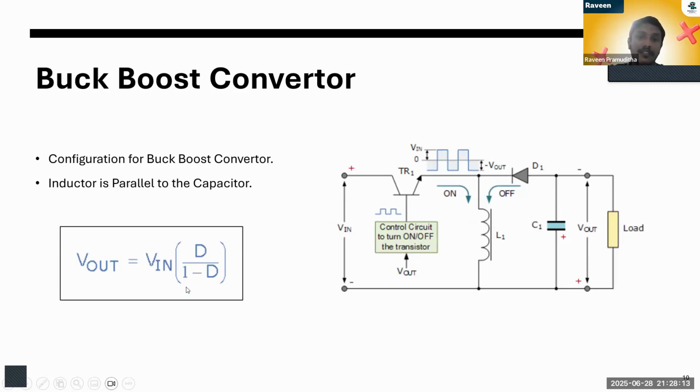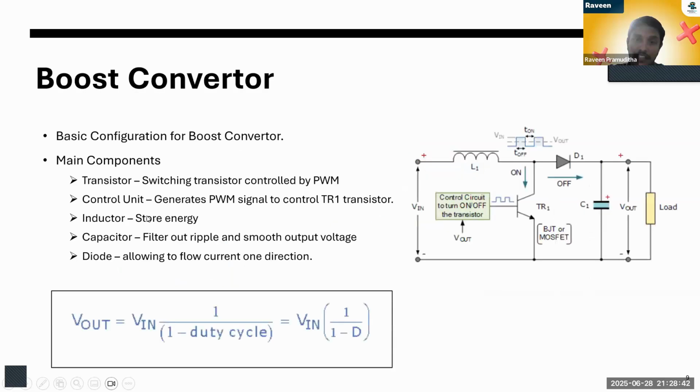So we can control that also using this PWM signal. When the PWM signal changes, that changes the path the current goes through, and this inductor stores the energy as a magnetic field. So when we give the relevant power to this circuit, that's what happens inside this switching mode power supply. So I think you can understand these things.